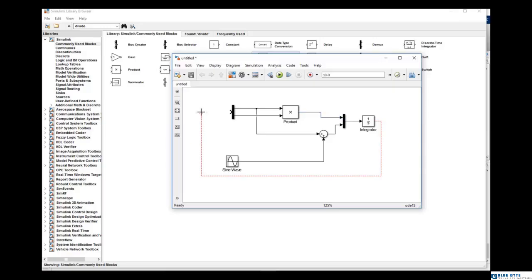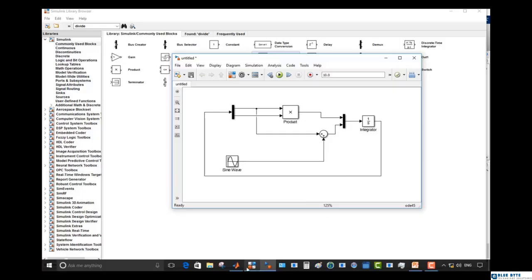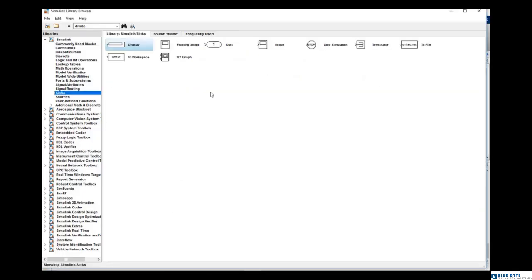Okay, here we create the x2 dot function which equals x1 plus sinus or u, and create x1 dot here that is equal to x1 times x2. We can use an integrator block and connect the mux output to the integrator input. Now we should use a scope in order to show the output.